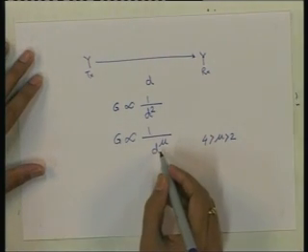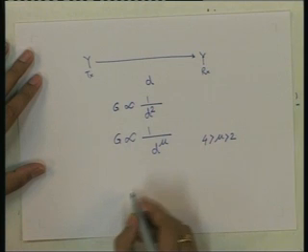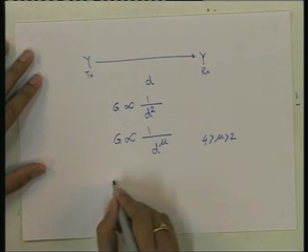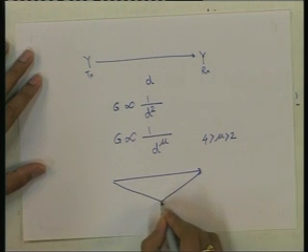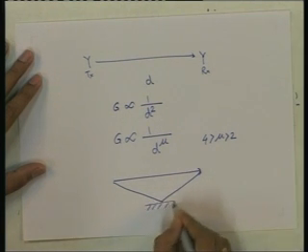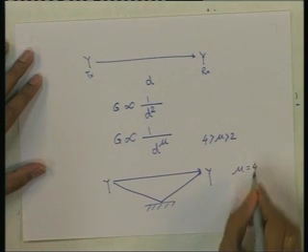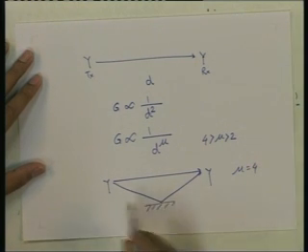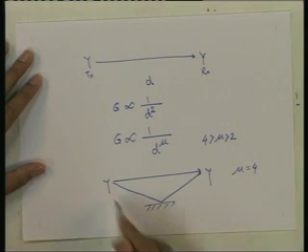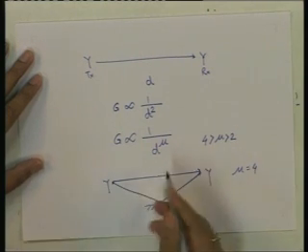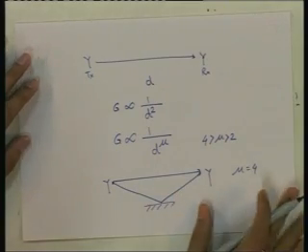Okay. So, for example, if there is only one reflecting surface, which is called the ground reflection model, where the signal passes, there is one direct path and there is one reflected from the ground, then mu is 4. So, the channel gain is proportional to 1 by d power 4. So, it depends on the environment usually.